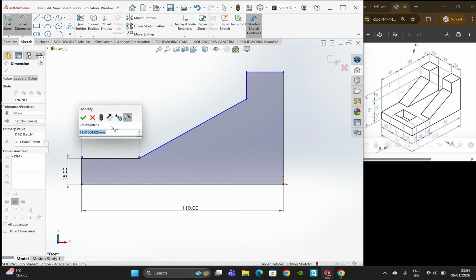Now, it's very important, if you select the slanted surface and we want to remove material, whatever shape we draw on it, we'll just cut a hole into it. Now, I don't want you to do this, but just watch what happens. If I click that surface and I sketch, and let's say I did something like this, and you thought that looked correct. The problem is when you cut into it and you go extrude cut, it'll only cut down through it at a weird angle, which is not the one we want. So that's not the one we're going to do. I'm going to exit that and delete it. Right click delete. So you don't have to do that.